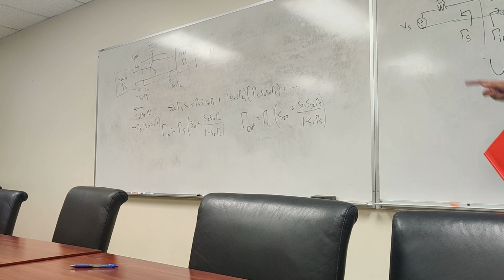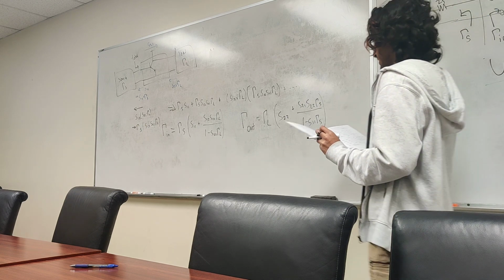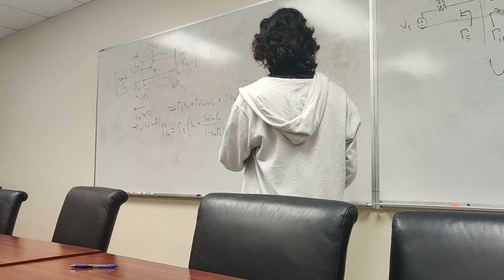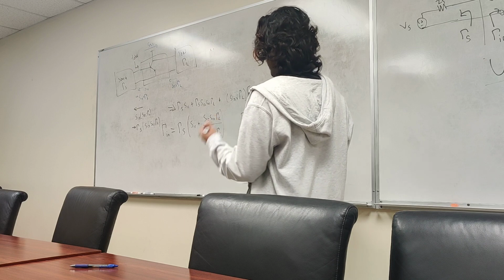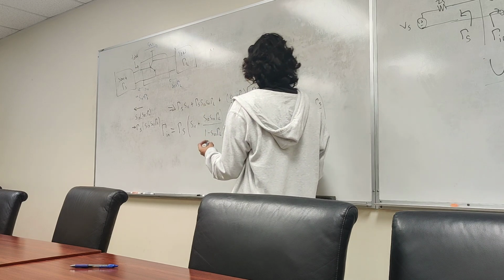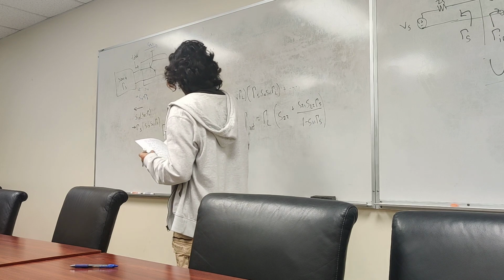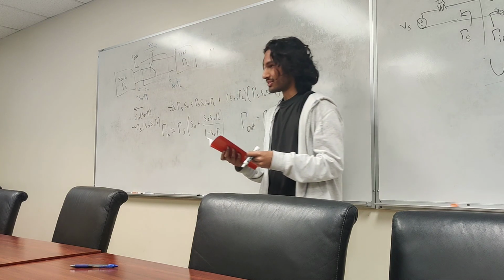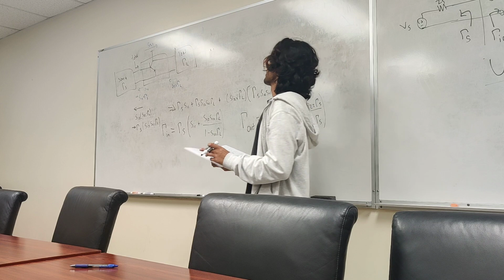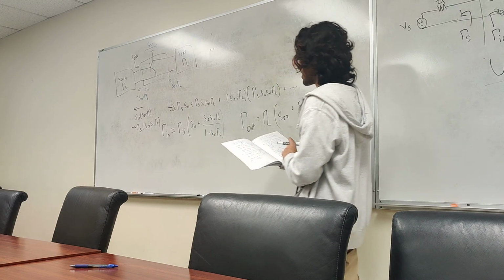So visually, if we can draw some boundary out, then it helps us visualize what's happening. Okay? That's just the intuition as to why, worst case, it's helpful to be aware of where our boundary is. It splits the plane into two. So I'm going to introduce a term called the stability circle. And the stability circle is the circle for which we say gamma in is equal to 1.